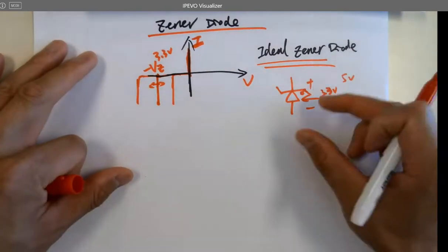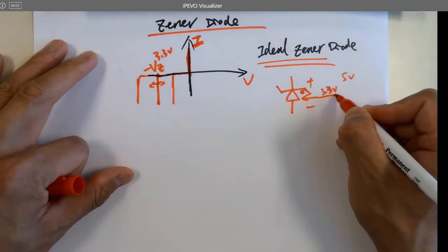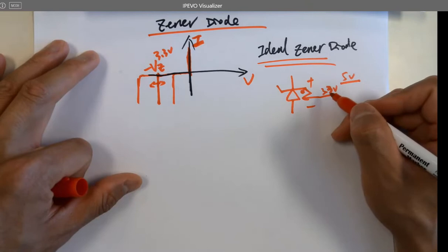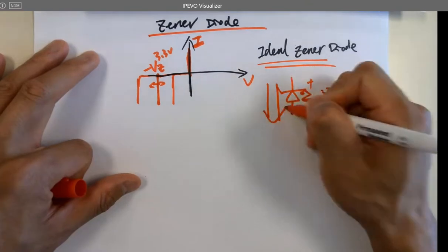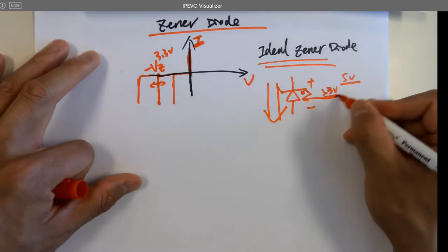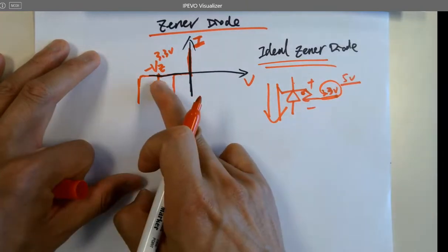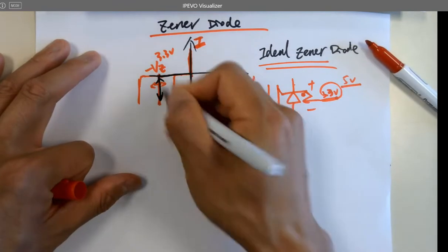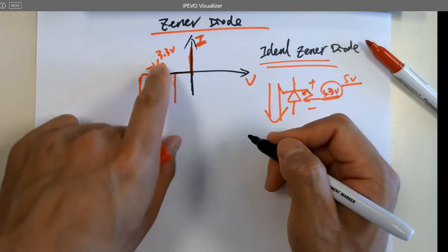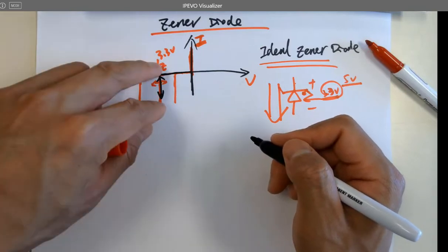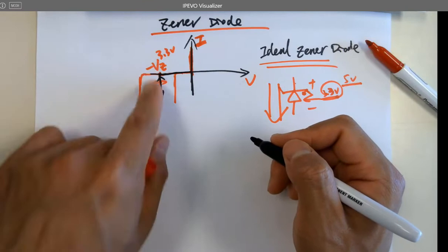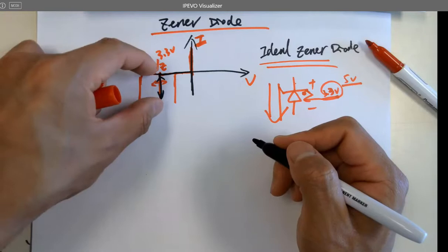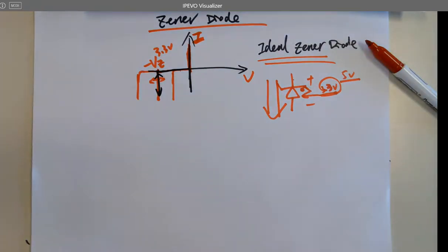For example, it's going to stabilize at 0.3 volts, right? But whenever the voltage becomes higher than that, it's going to draw a lot of current in order to drop that voltage down to VZ. After that point, it's going to just follow that curve here, but not move anywhere else, right? Just stay at VZ, changing the current. If you're trying to increase the voltage, it's going to bring it back down to 0.3, but changing the current, right? So that's the ideal Zener diode.